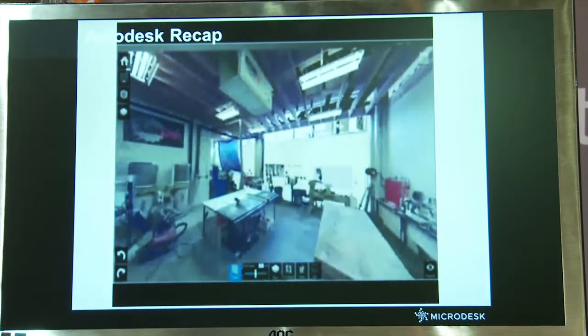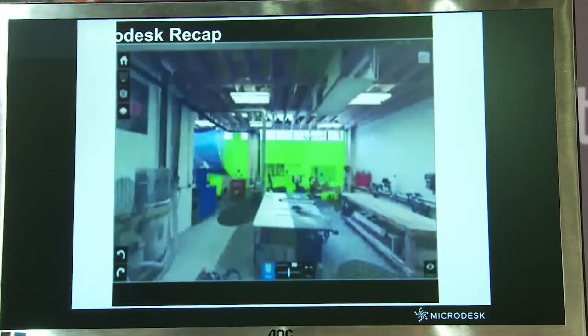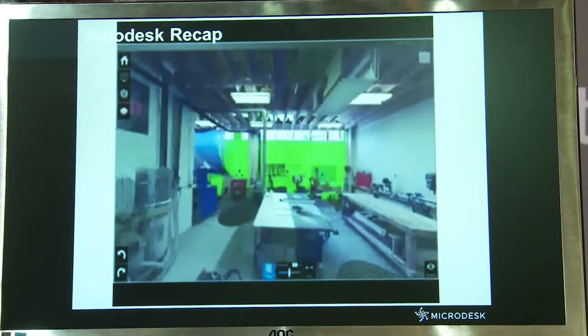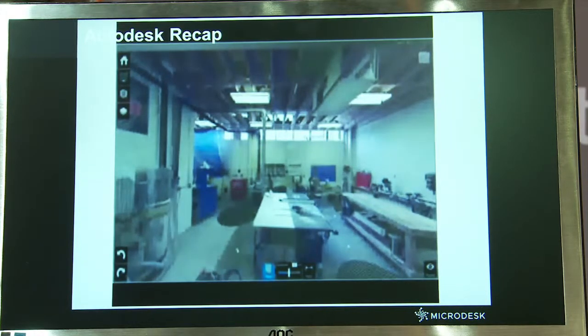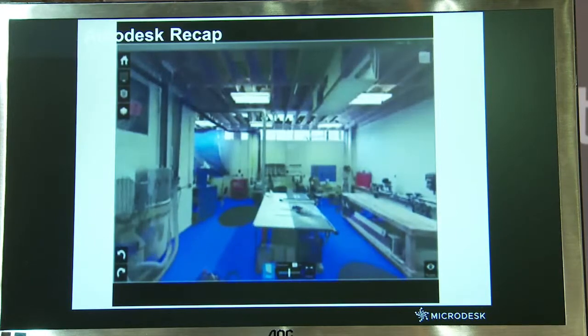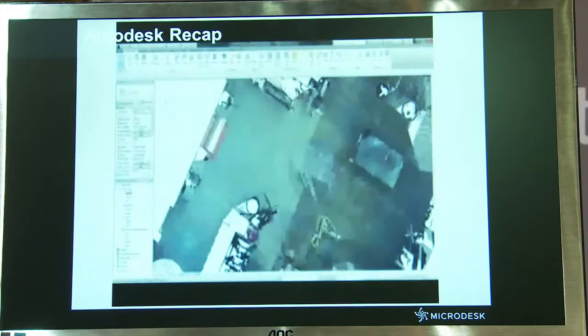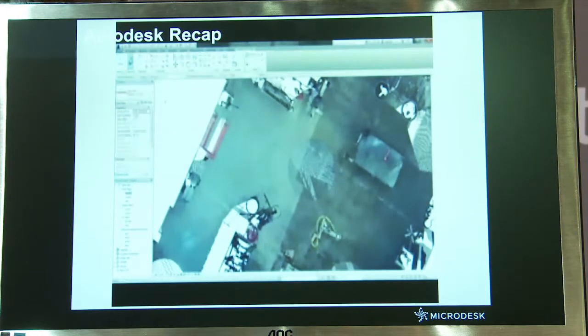They also have a version called Photo Recap, which allows you to bring in images similar to how Autodesk 123D Catch does it, but directly in Recap, so you have a little more control. You can color-code it and layer it, so you can say this area is building aisle 1, or west wing versus east wing, so you can break it up if you want to, and you are still able to later bring that into Revit and snap to it.